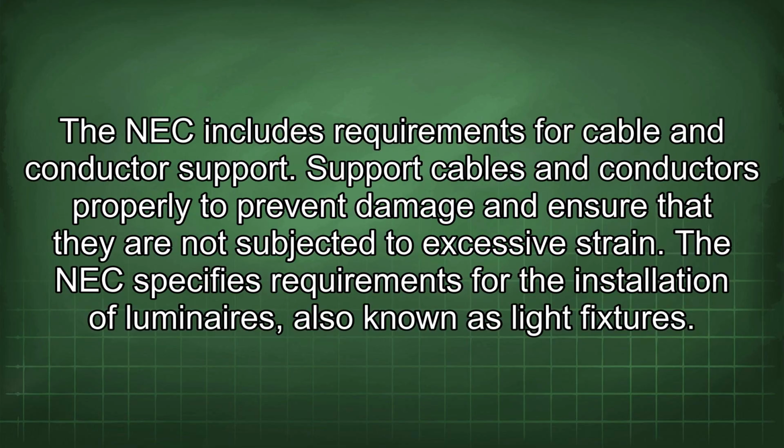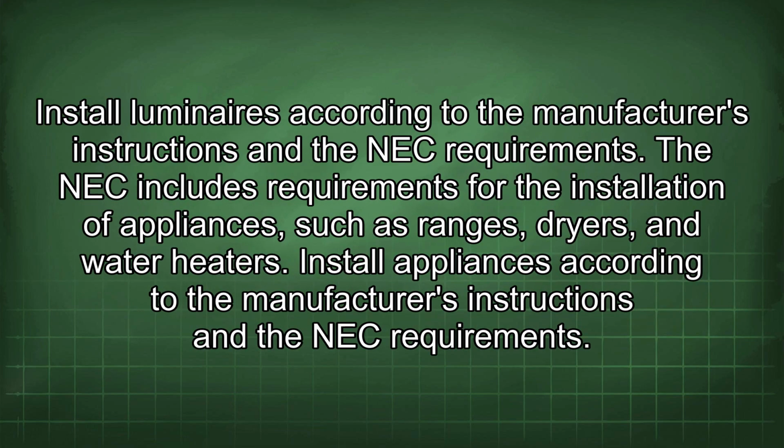The NEC includes requirements for cable and conductor support. Support cables and conductors properly to prevent damage and ensure that they are not subjected to excessive strain. The NEC specifies requirements for the installation of luminaires, also known as light fixtures. Install luminaires according to the manufacturer's instructions and the NEC requirements. The NEC includes requirements for the installation of appliances, such as ranges, dryers, and water heaters. Install appliances according to the manufacturer's instructions and the NEC requirements.